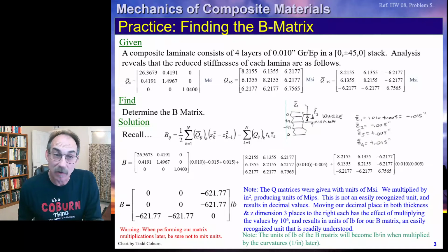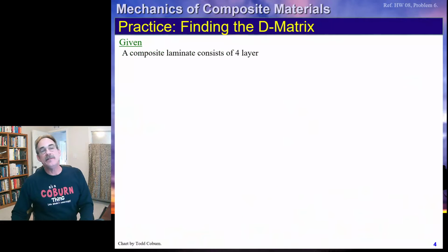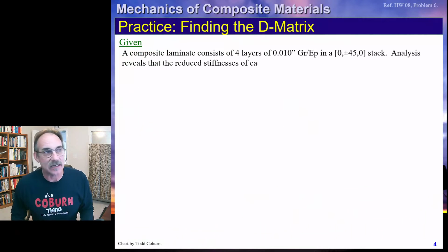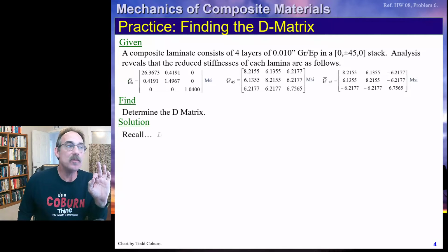And this is a little warning about mixing units. Whenever we're reporting numbers with different units, it's a little dangerous. We've got to be careful. The D matrix, we're going to start with the same laminate again. We have the same Q bars.